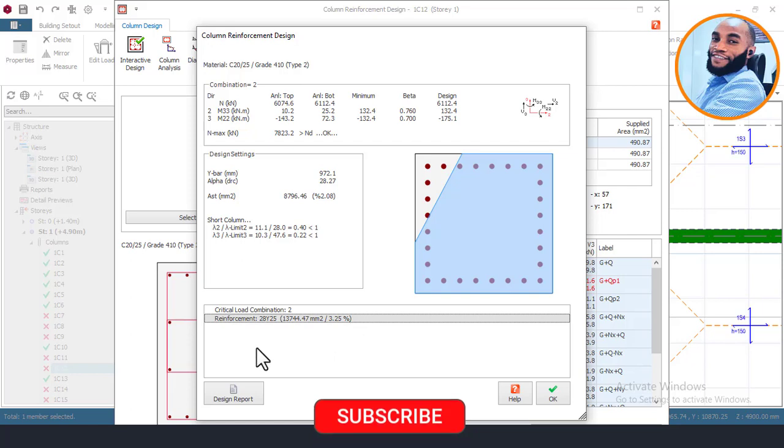Okay, so right now you can see that it used a critical loading combination of 2, which is actually the maximum on this column, to design for that. And you can see that the reinforcement now produced for the column is 28 numbers of Y25. So once you are able to see your reinforcement without any warning again, then that column is okay.